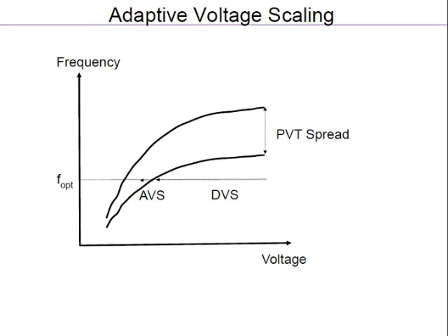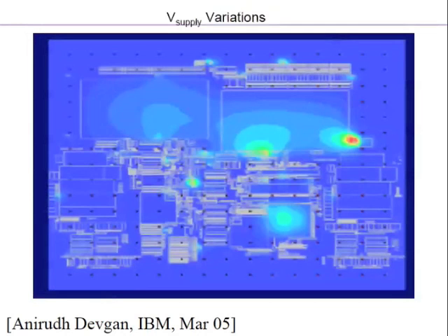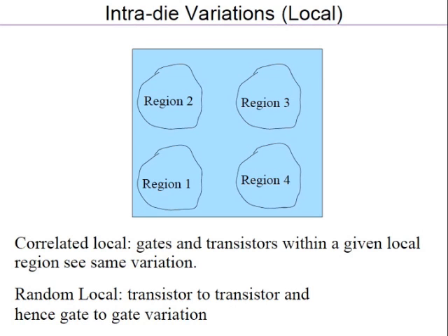You can also have ring oscillators which are spread out. Here we saw how you have 4 different regions, right? Maybe you have separate voltages for each region, multiple VDDs within the same chip, and each one you characterize, and then each one has its own customized voltage.